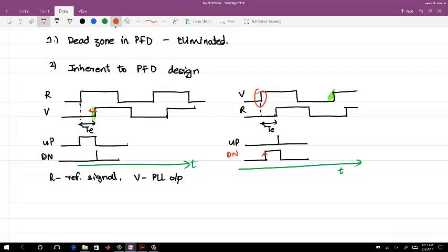Got that? So you see, for the same input, at the instant of the reference, whatever the delta phi error was at the input, it depends on whether it's positive or negative, what you are correcting. Had the system been linear, it should be just a linear gain in the system. So one part will be faster, the other will be slower if you look at the settling point for any given phase error.